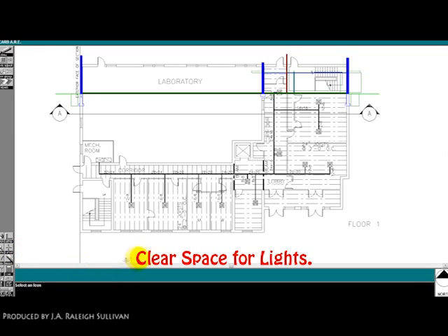So we look at the plan and see the joist sizes called out. 24-inch joist at 2 feet on center here, and it looks like everywhere else. And then we look at the ducts, and it looks like the largest size is 32 by 24. Look around a little more to make sure that we're not missing anything. In this case, it looks like these really are the largest ducts and joists, so we'll use them.